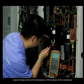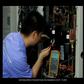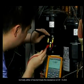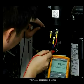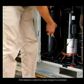Solution. Measure the terminal resistance of 3-phase of the compressor. Normally either of 2 terminals the resistance is 0.9 to 5 OHM. The resistance between terminal and ground should be more than mega OHM. That means compressor is normal. If the resistance is abnormal, please change the compressor.